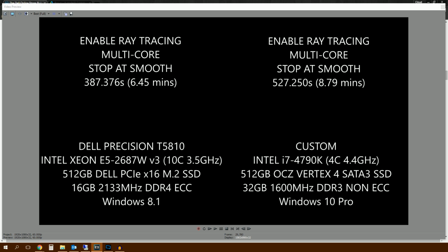Even since doing these tests, I've bought Dell Precision Workstations for the office that I'm in, purely because they're supported systems. The gaming PCs, they may perform better marginally, but you can't realistically put a gaming PC in a professional drawing office. You still have to go for those Xeons, you still have to go for that ECC reliable RAM and those Quadro cards, because Autodesk, when they perform tests on their new software that comes out, they only benchmark test the Quadro cards and the FirePro cards. They don't benchmark test or certify drivers for gaming cards.